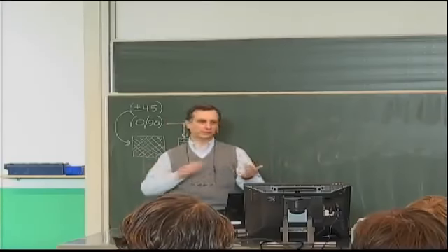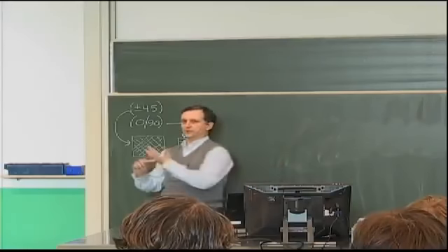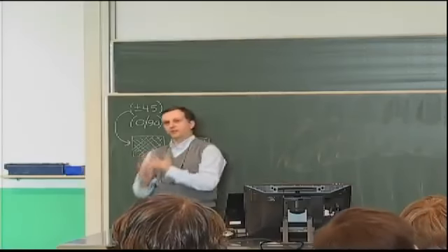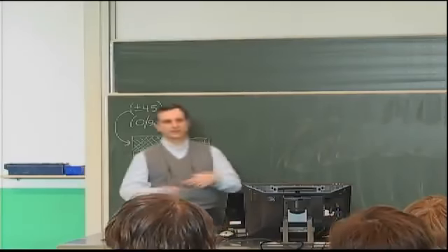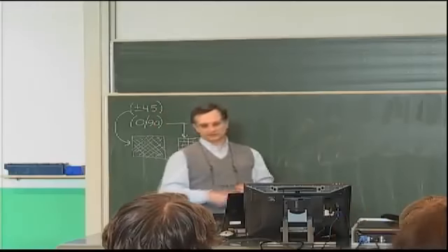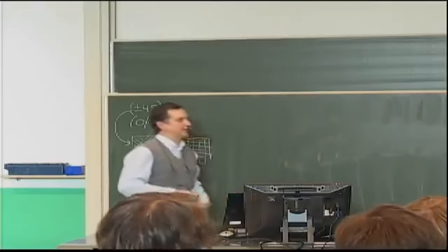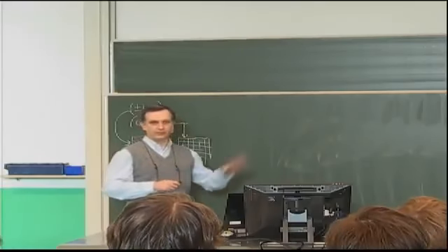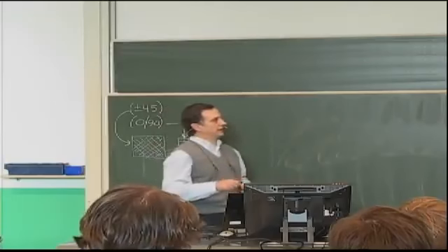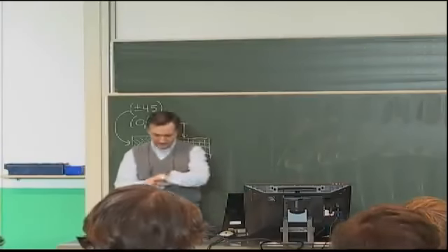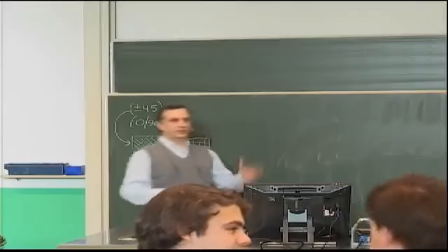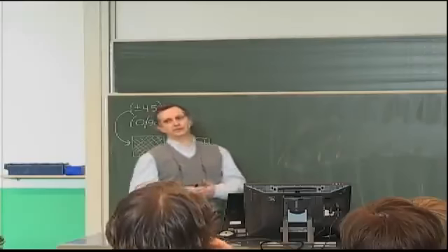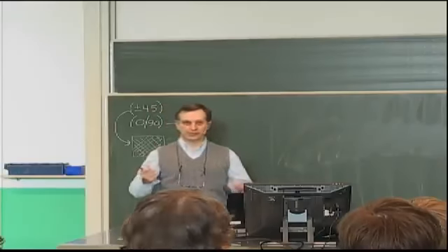So you have an option. Either you develop the intuition, and then you just do finite elements and use your intuition, or you develop enough understanding of the basic methods that you can use to check solutions like your finite elements. One of the methods is energy methods. We have 2 types of energy. In fact, we have a whole bunch of them, but the 2 of interest are the potential energy and the complementary energy. And basically, you can minimize either of them. Potential energy basically means you write your energy in terms of displacement. Complementary energy, you write it in terms of stresses or forces.